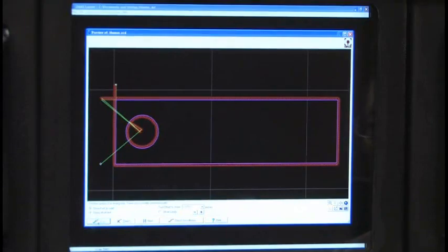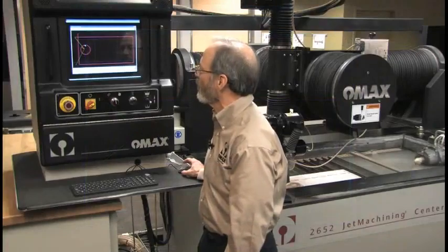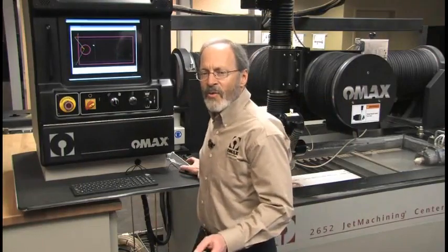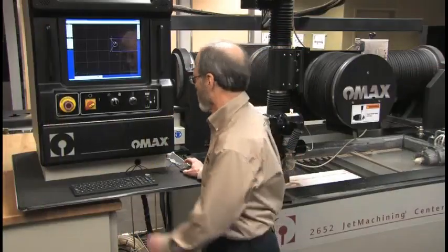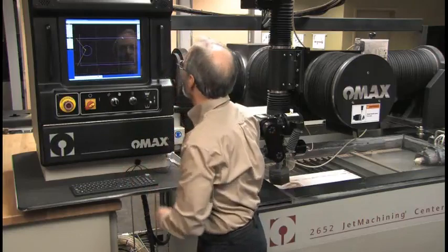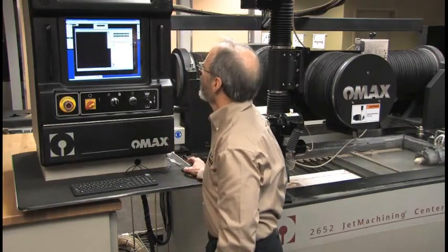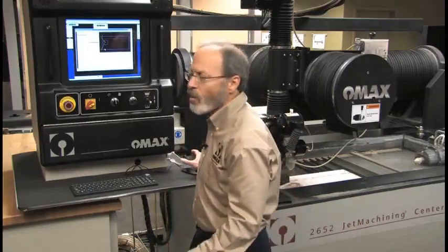It's going to cut on the inside of this hole, so I get the exact size I want, and on the outside, so I get what I want. This is also where I would find out if there was a problem with my drawing, say two lines that didn't connect. But that's fine, we can go ahead and save that. And now we'll go to where the real action is, and that's the make part of the program.